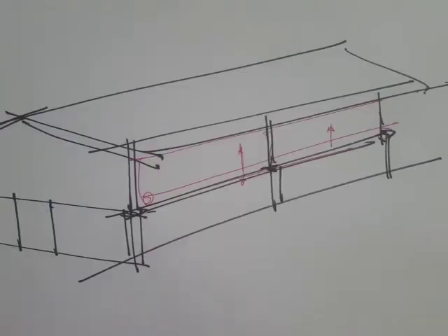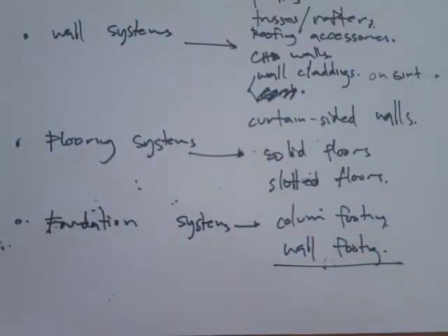Okay, so now let's move on to our flooring systems. Typically, the agricultural building is just a one-story building, meaning that our slabs are designed as slabs on grade, so we don't worry about second floor slabs or elevated flooring using concrete.